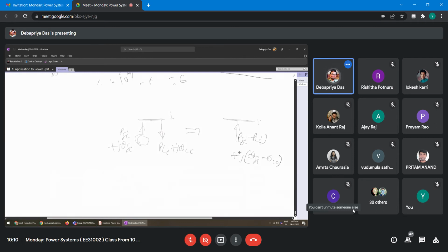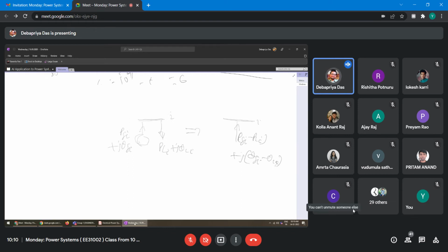Similarly QGI minus QLI. If you take the other direction, it would have been PLI minus PGI, then QLI minus QGI. This is the net power injection for any bus, right? So this is PGI minus PLI, and this is j(QGI minus QLI), because this power is being injected.